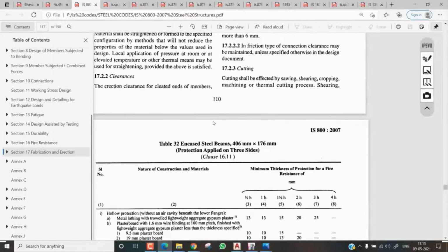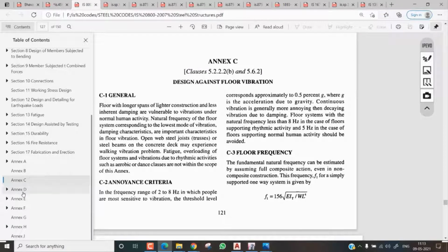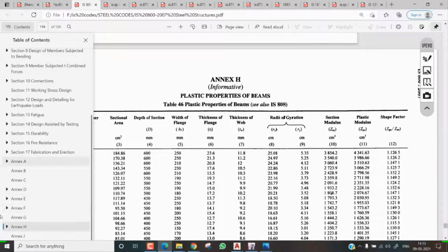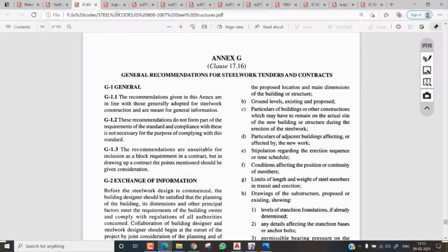Erection is also a very important thing, and whatever the designer gives matters; if it is correct, no need to worry about erection. Suppose the designer or detailer gives wrong inputs or wrong drawings, then the erection team may suffer and needs to face a lot of issues due to improper detailing and drawings. So we need to be very cautious about the design. In RCC we can still make corrections, but in steel, once it is fabricated, we can't do anything. We need to cut apart the entire plates and refix them, which leads to higher cost.